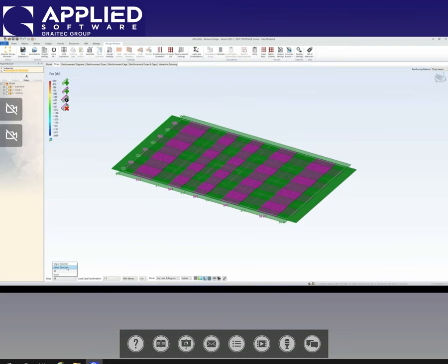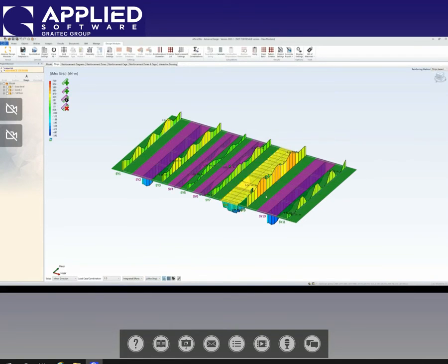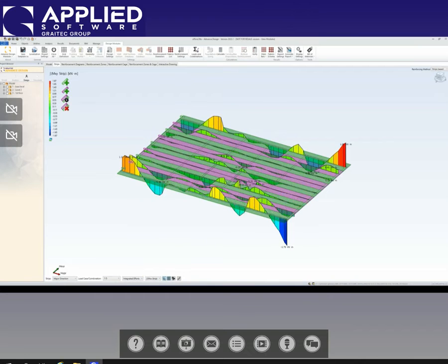So for example, we can go here, and now I can select what type of forces I want to see for each strip. So it's going to show me all of them. So we can go to also major. So this is going to be my moment on each strip separately. So we can select all of the results that we want to consult to perform our strip design.